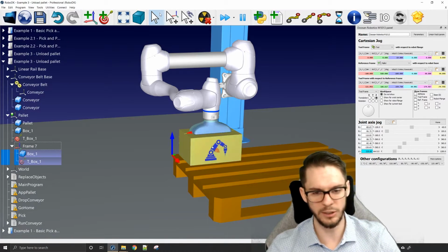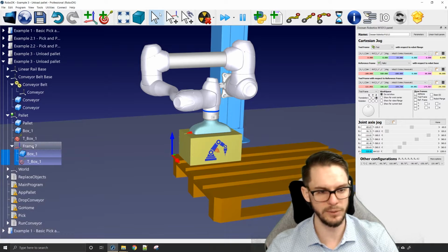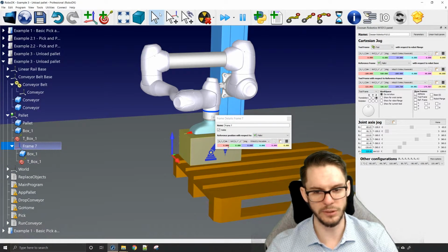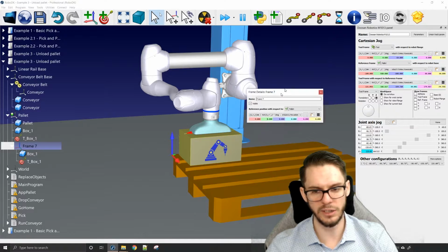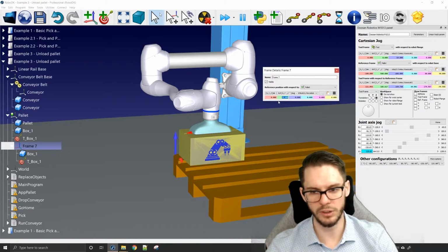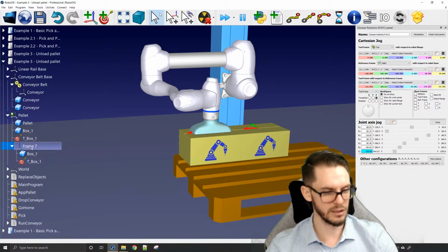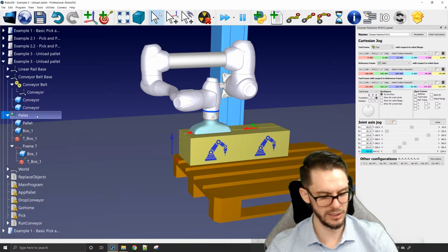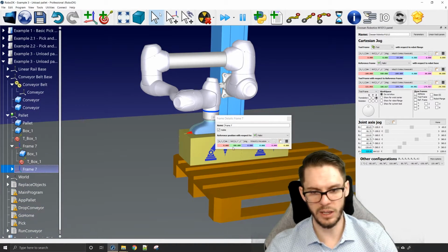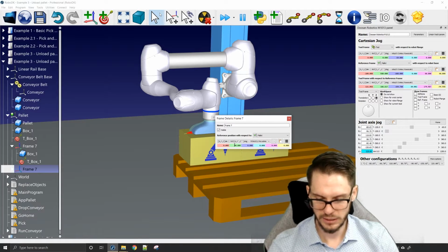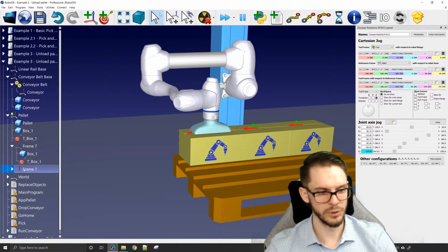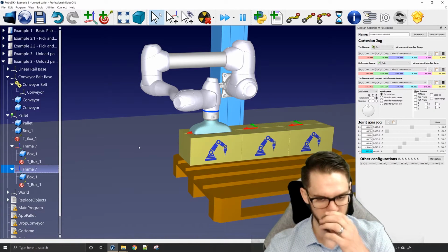So now I have it duplicated on top of it. I'll just click the reference frame, and I know that this box is 300 millimeters long, so I can bring that to 300 millimeters. So more than just having the new box, I also have the target with it, so this is interesting. I'll Control-C and Control-V again the reference frame, and now I'll place it at 600 millimeters. Perfect. Cool. Now I have that.